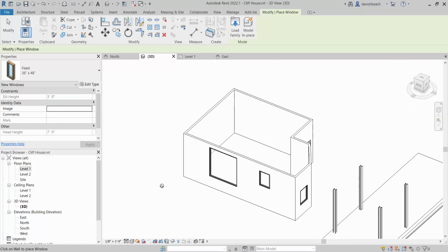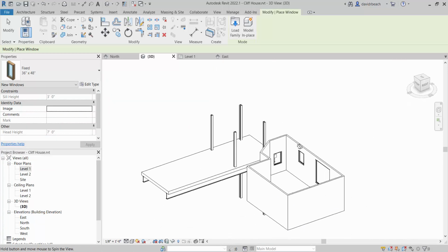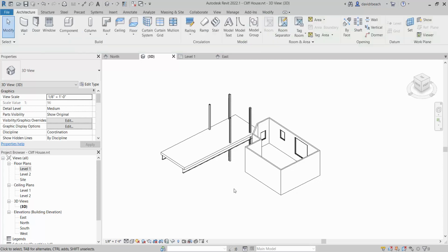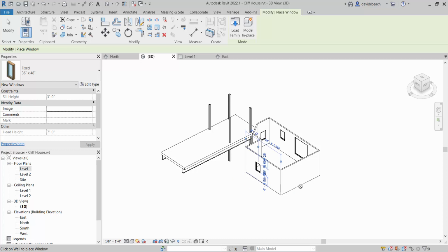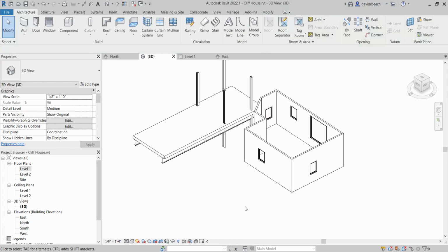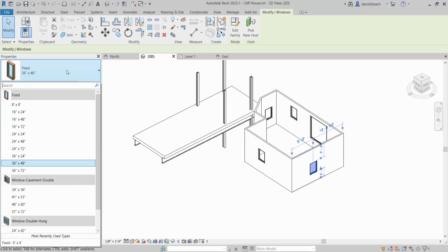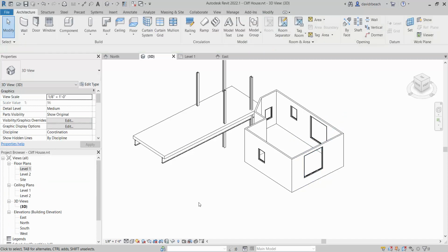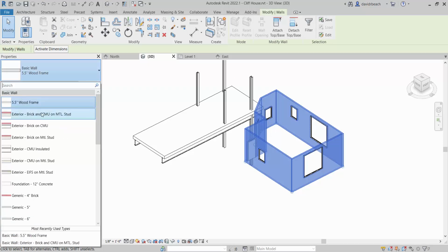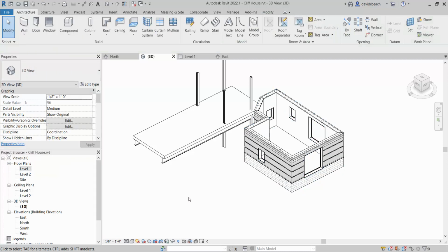So the other important thing to note in Revit, this is my parting thoughts, and then we regroup Wednesday. Nothing really due between now and Wednesday, okay? Other than getting caught up if you don't have the base created. At any point in time, if I have a window in my scene, I can select that window and come back to my menu and change it to 8 by 8. Those models are made to be dynamic. At any point in time, I can select all of my walls and say all of those walls actually should be exterior brick and CMU. All of those things change dynamically.